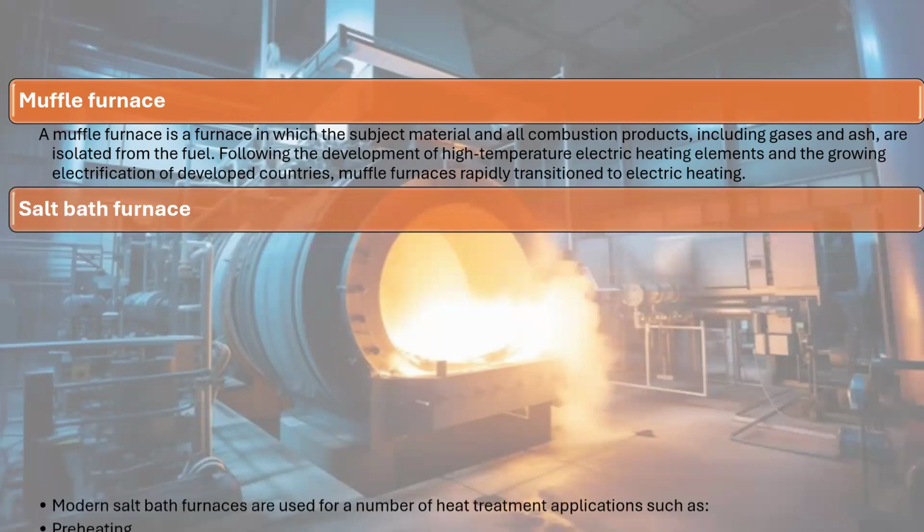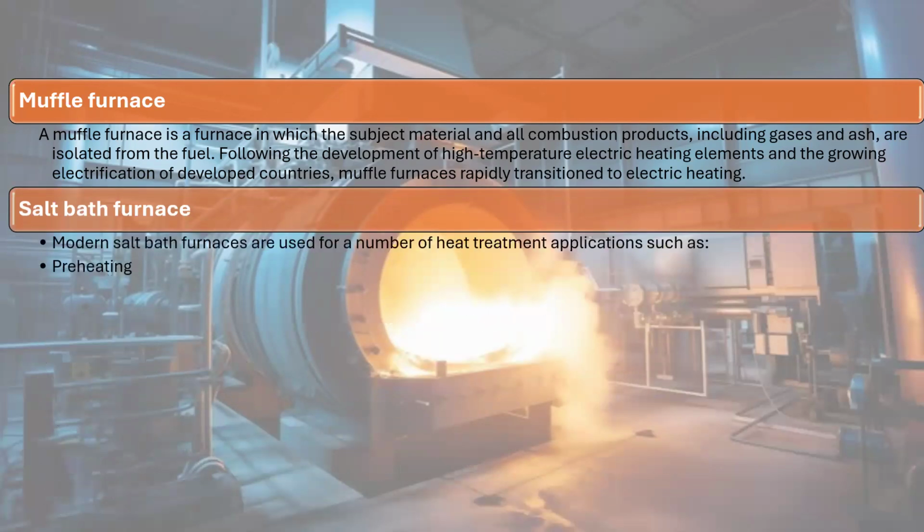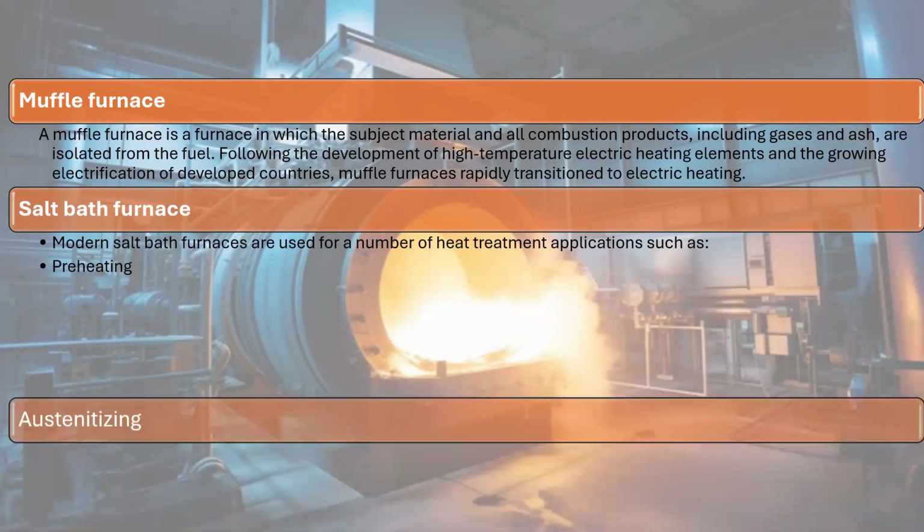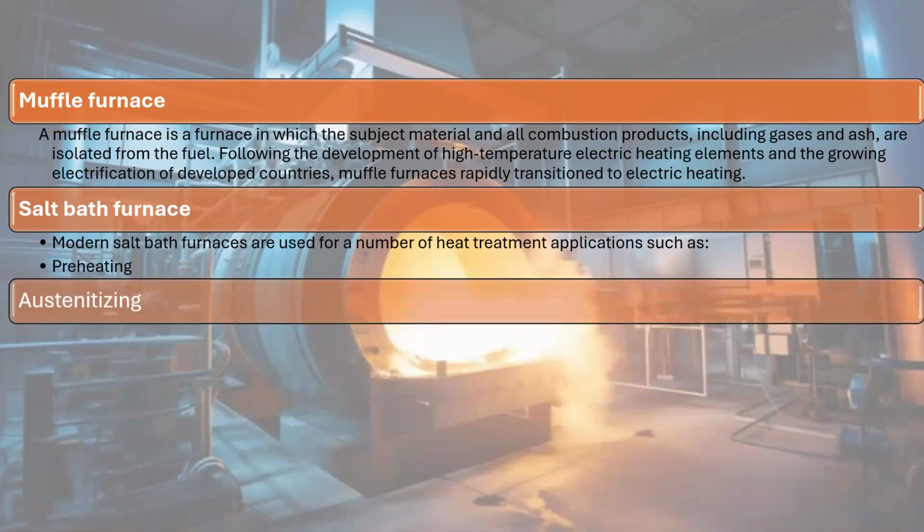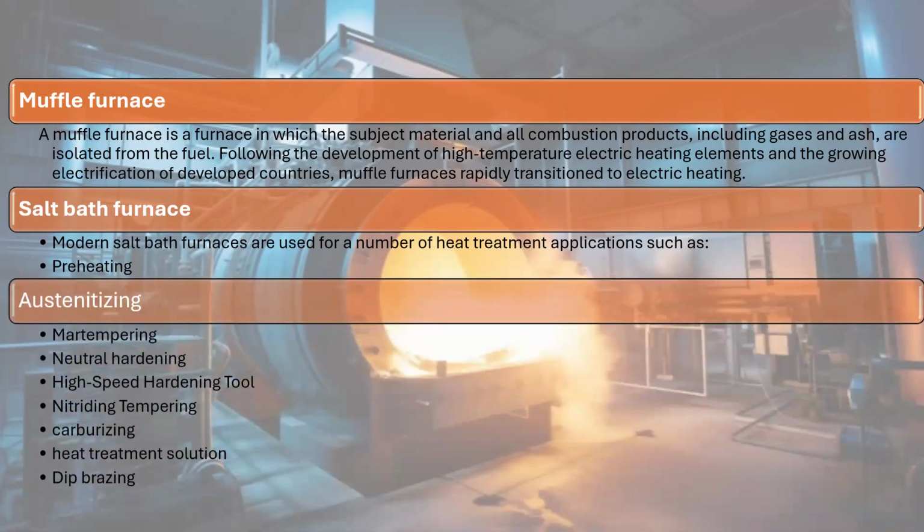Salt bath furnace. Modern salt bath furnaces are used for a number of heat treatment applications such as preheating and austenitizing, mass tempering, neutral hardening, high-speed hardening of tools, nitrogen tempering, carburizing, and heat treatment solutions. And the last one, dip brazing.